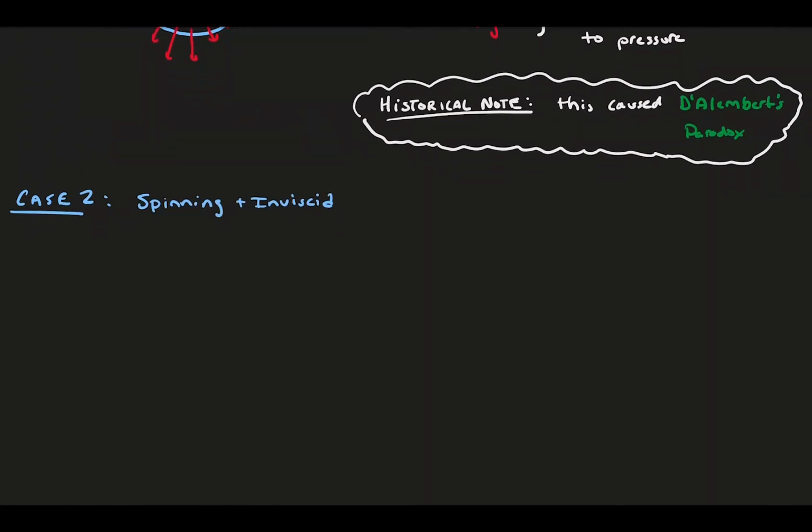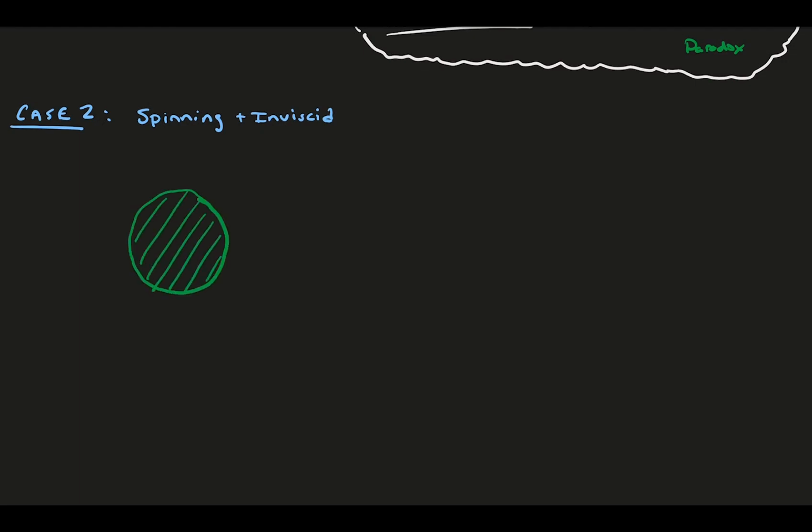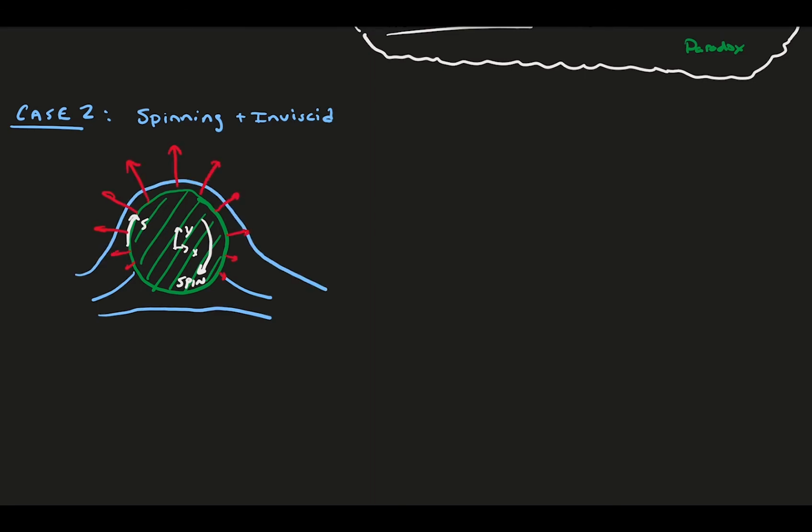When a cylinder rotates, the stagnation points move down on the cylinder and more air passes over the top than the bottom. This results in a pressure distribution that looks something like what you see here. There are regions of high pressure magnitudes at the top and lower magnitudes at the bottom. Still, the pressure distribution is the same when comparing the front and back of the cylinder, mirrored across the x-axis.